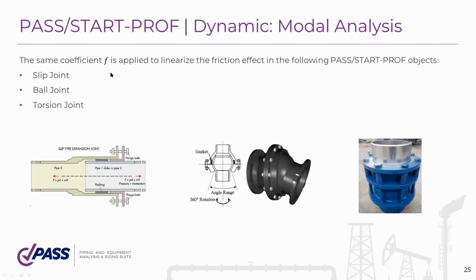Also, START-PROF applies this friction factor to expansion joints that have friction inside. These are the slip joint, ball joint, and torsion joint. START-PROF automatically applies this factor for expansion joints too.